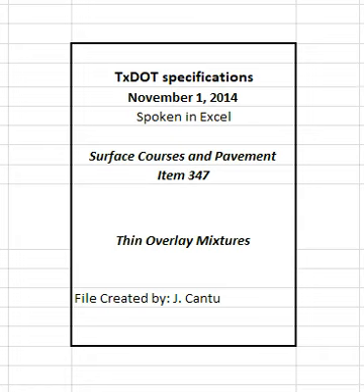Suspend production until further Hamburg wheel or overlay tests meet the specified values when the production or core samples fail to meet the Hamburg wheel or overlay test criteria in Table 7. Core samples, if taken, will be obtained from the center of the finished mat or other areas excluding the vehicle wheel paths. The engineer may require up to the entire sublot of any mixture failing the Hamburg wheel or overlay test to be removed and replaced at the contractor's expense.